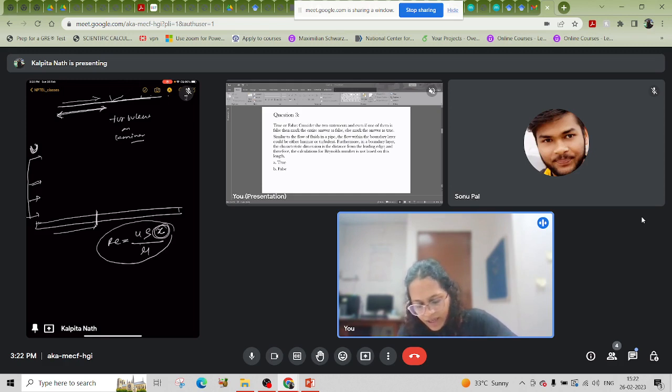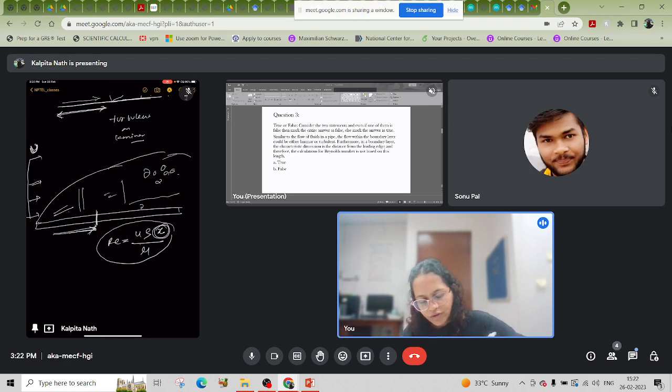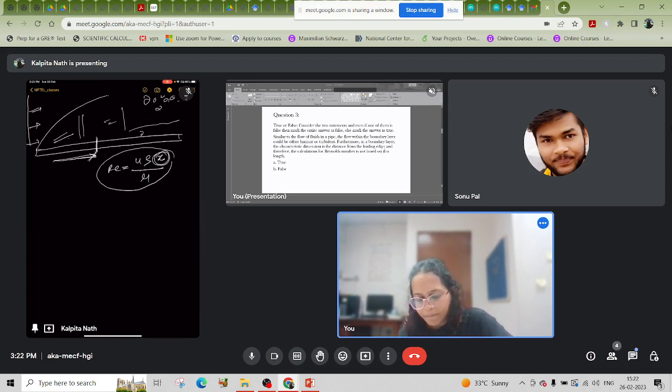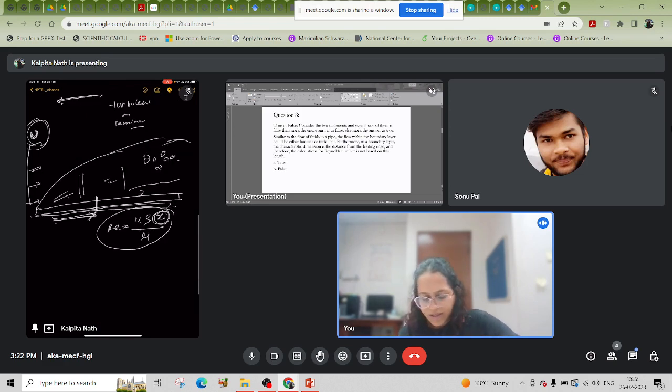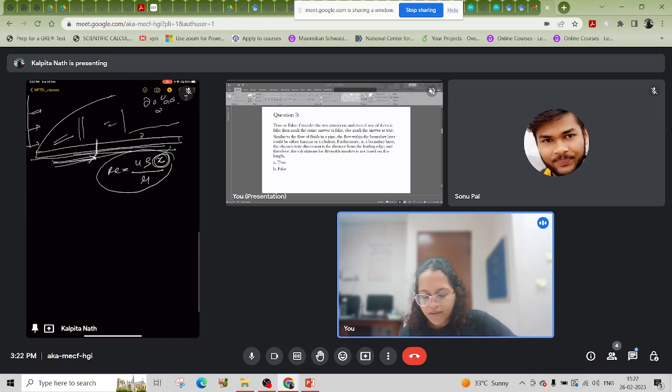So it depends upon the x, the distance. Here we can get laminar, here we can get transition, and here we can get turbulent, like this will be viscous sublayer and here eddies will be there. So Reynolds number, depending upon the distance from the leading edge and depending upon this velocity, it may change. So we can get on the same plate laminar flow, transition flow, and turbulent flow.